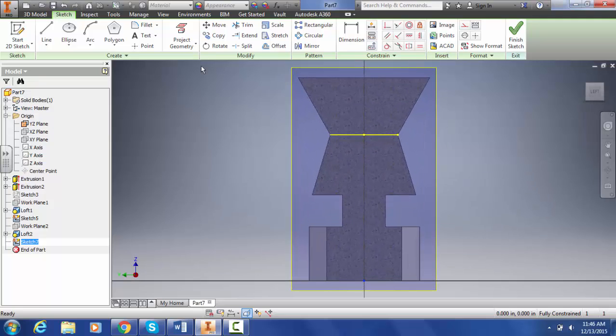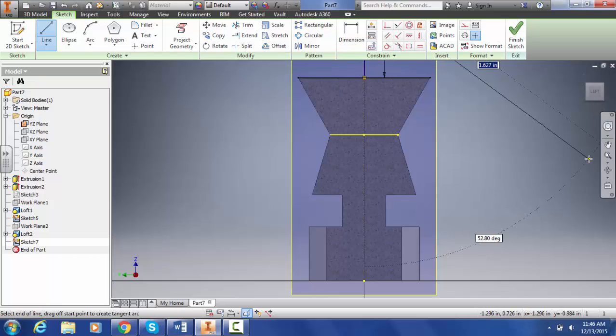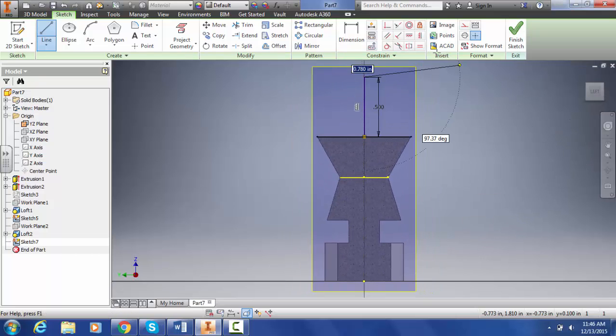So now I need to create the head. Just like I did on the male figure, I'm going to start here and go up 0.5. I'll go ahead and hit zoom all again. Then I'm going to use an arc tool starting here and just kind of randomly, they didn't give me measurements, so I'm just randomly going down and then clicking, and now I'm creating the curve.